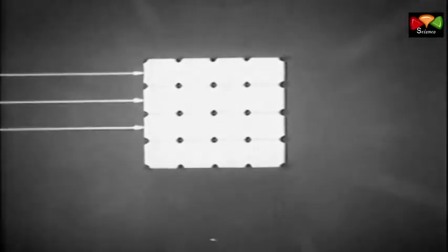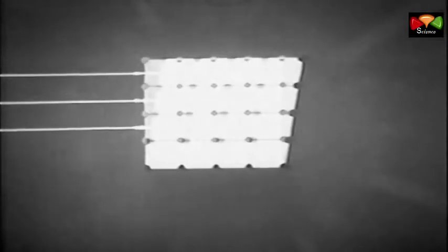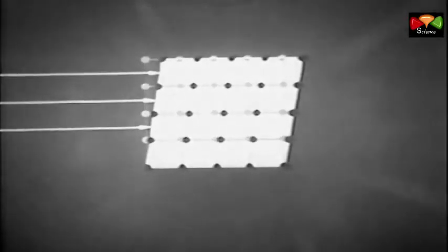Through such movement, a crystal may undergo two types of deformation. The first is called elastic deformation. When small external forces are applied to the crystal, atoms on the lattice are moved slightly from their normal positions, and the lattice structure is skewed. When the forces are removed, the atoms return to their original positions, and the lattice recovers its normal shape.